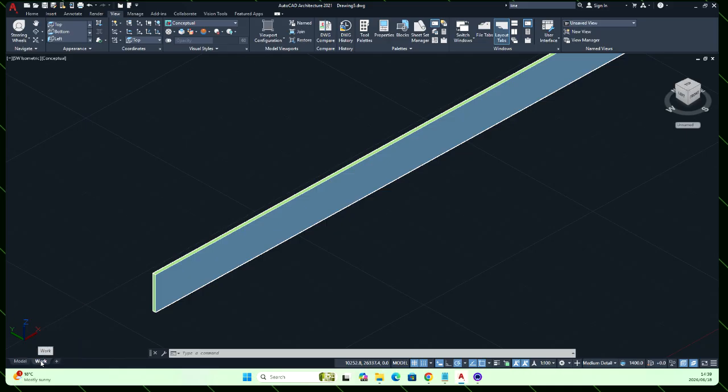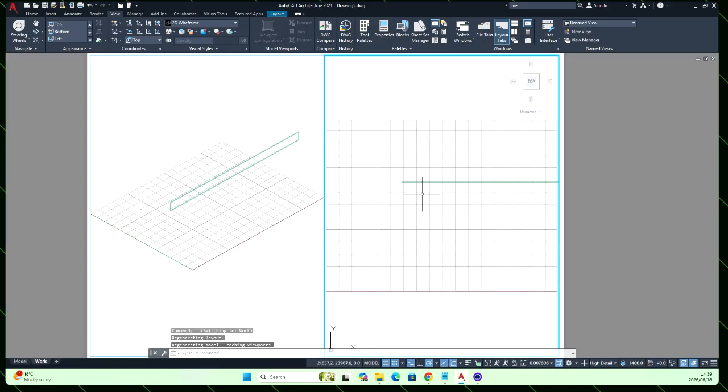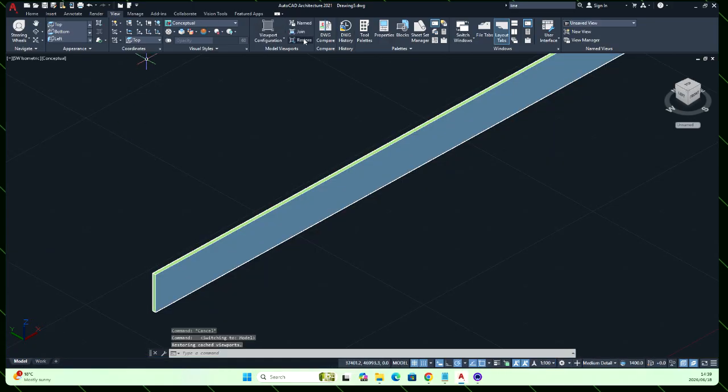And that will cover when we get, yeah, so this is a viewport and that is a viewport, right? DWG compare, if you have two revisions and you've made changes on the one, you can actually use that to check what has been changed, so you're sure that you didn't miss anything, right?